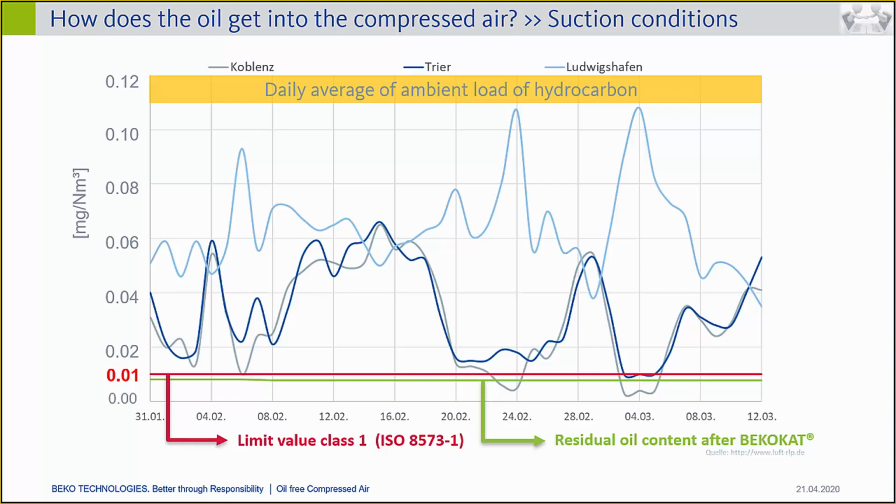To measure how many silicon-based molecules you have left in the air, there's simply no way, except taking a sample and putting it to a laboratory afterwards, and then this sample is again months and weeks old. As far as I remember, we had some customers who had problems with silicon in their compressed air in the past, for example, again in the car painting industry.